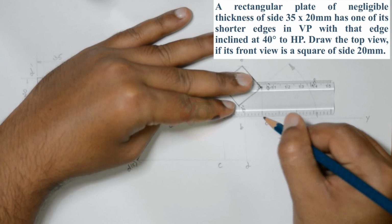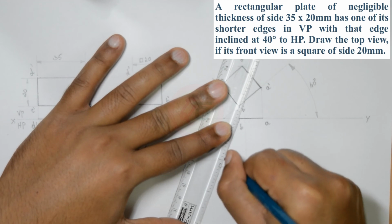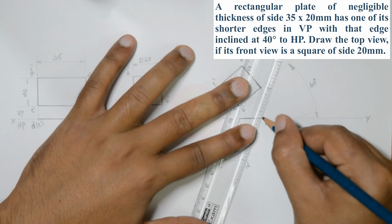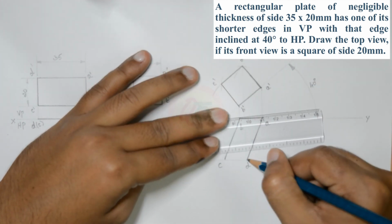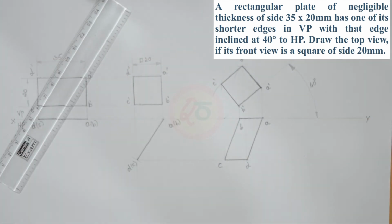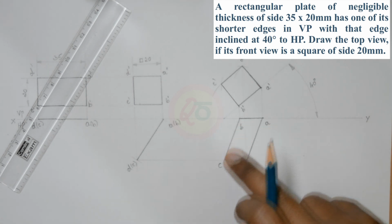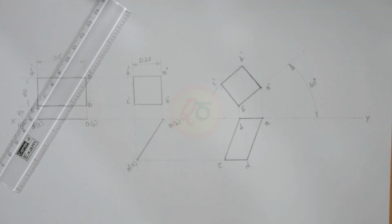AB, from B to C, from A to D, and from C to D. Okay, so this is the final projected view, which is the top view. It will look like a parallelogram. AB should be equal to CD and AD should be equal to BC. Okay, this completes the solution for the given problem.